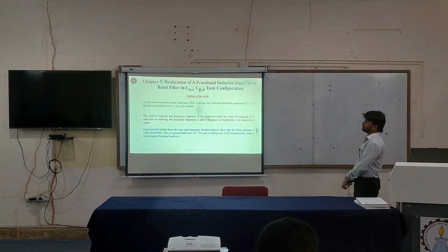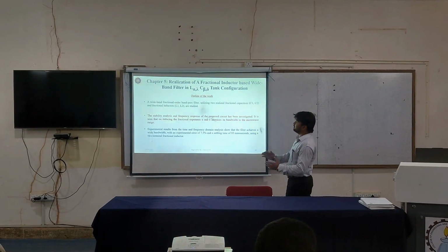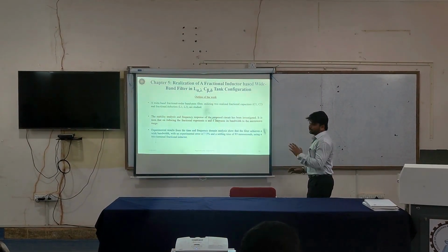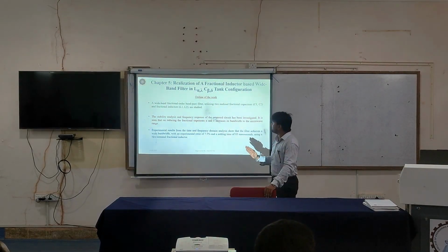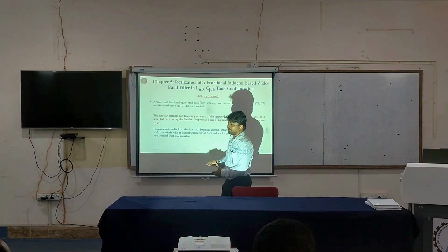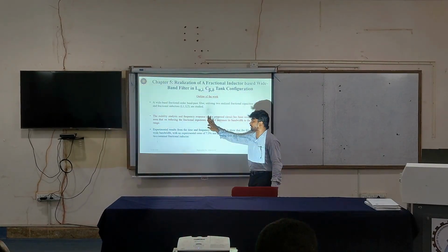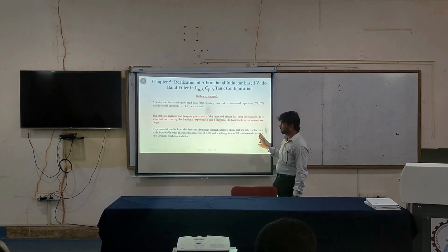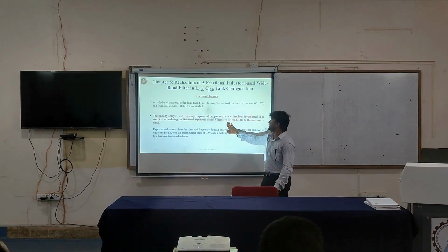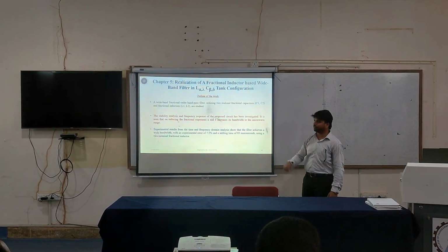That is the realization of a fractional inductor based wide band filter using LC tank configuration. Here, the wide band fractional order bandpass filter using 2 realized fractional capacitors and 2 fractional inductors has been used. The stability analysis and the frequency response have been investigated. It is seen that reducing the fractional exponents, that is alpha and delta, increases bandwidth to microwave.